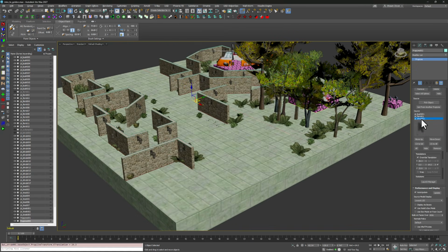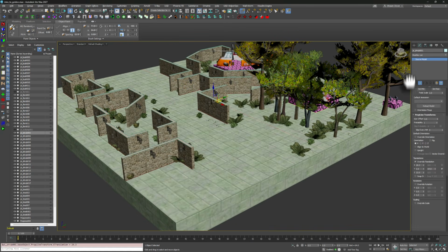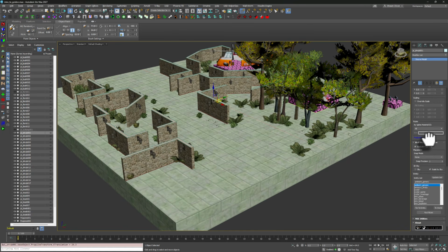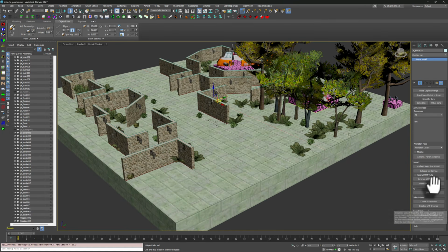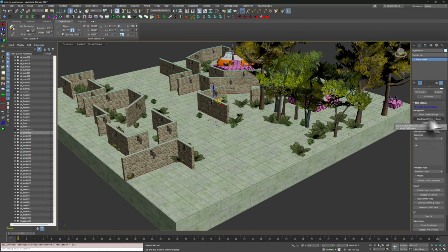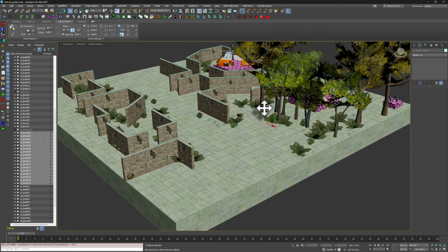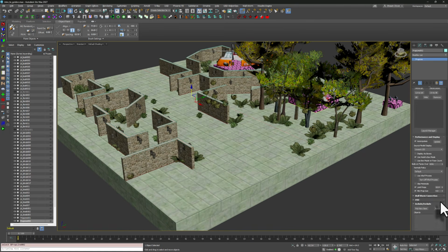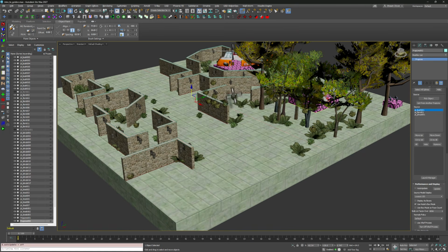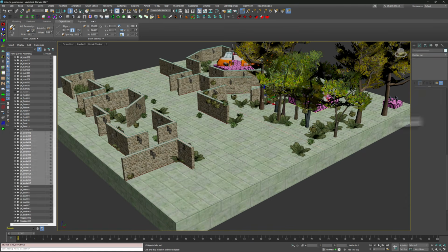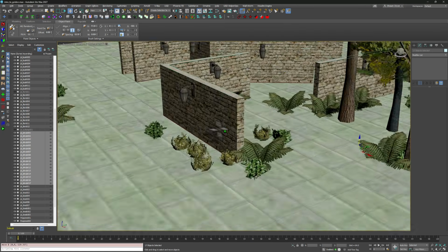To quickly move up all the ones that I had object painted, I select one of the bad props, scroll down to the MDL Utilities rollout in the Modify tab, and click the Select Same Model and Scene button. With all of these selected, I move them all up. They were all laggy to move because they are all instances of objects used in a prop line. By selecting that prop line and turning off auto update, I can then easily move these props.